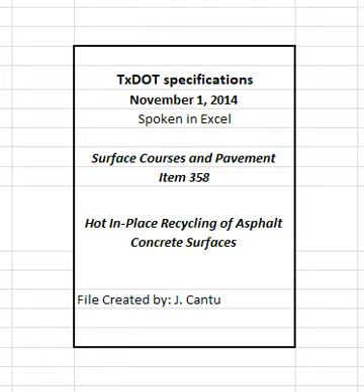4.2.4 Aggregates. If necessary, use aggregates meeting the requirements in Table 1 of Article 340.2, Materials, or as shown on the plans. 4.2.5 Additives. Other additives may be allowed to meet the requirements in Table 1. When other additives are used, document the type and percentage in the mixture design submittal. Table 1. Laboratory mix design properties. See table in specifications. 1. For informational purposes only. 2. Used to establish a baseline for comparison to production test results. 3. May be reduced when approved.